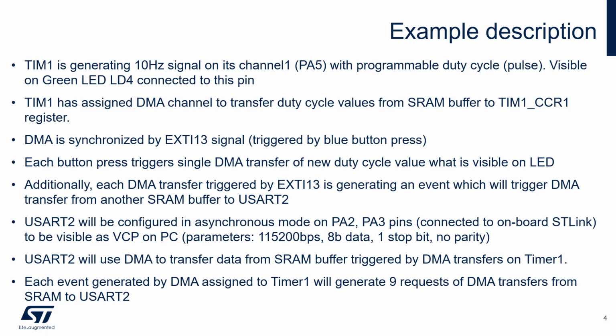All the transfers between SRAM buffer to timer 1 capture compare register 1 will be synchronized by the external interrupt 13 signal coming from the blue button. So each blue button press will trigger the copying of the new pulse value from the SRAM buffer to timer 1 capture compare register 1. At the end of this transfer,